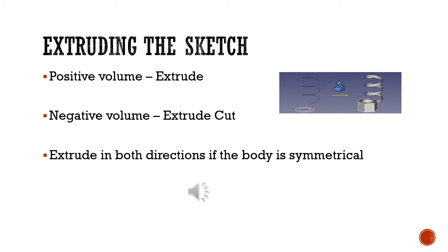Also, I would remind you that if you have a part that's symmetrical, I recommend you extrude it in both directions. It gives you a lot more flexibility down the road with your part that you've created.